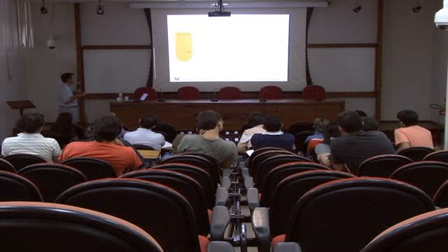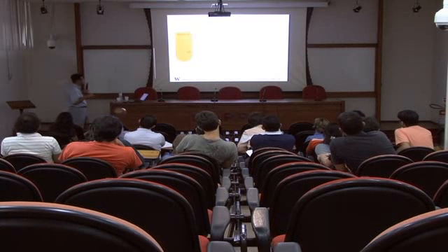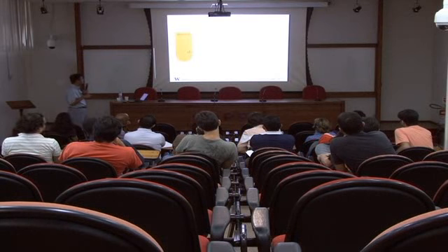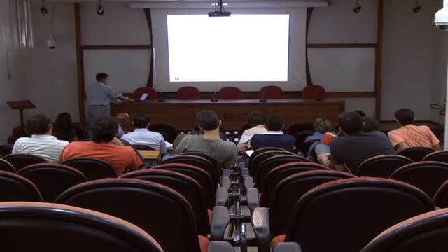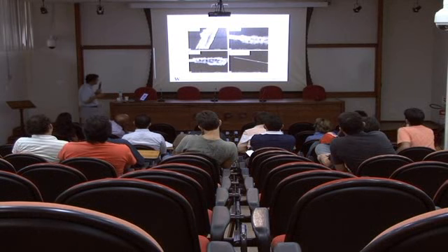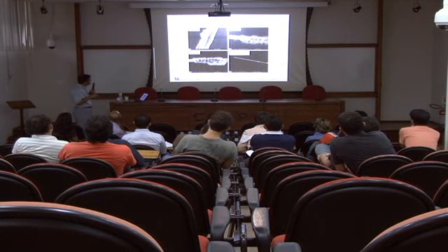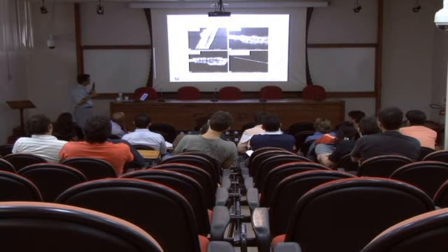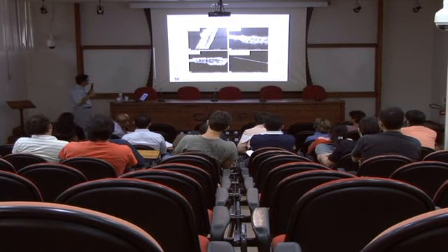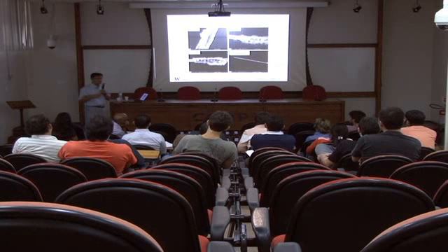So this is a rough mathematical model, and we calculated the capillary force induced on this particle, and also we calculated the force for viscosity. And in experiment, what we found on a nanotip surface was, for example, if the diameter of this tip is 360 nanometer, then we could capture particles up to 125 nanometer diameter.